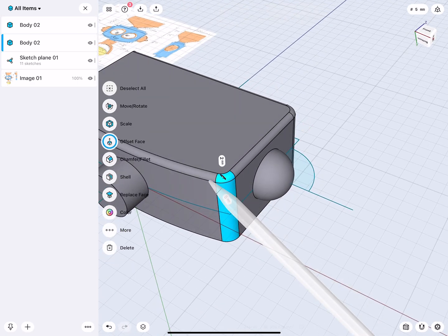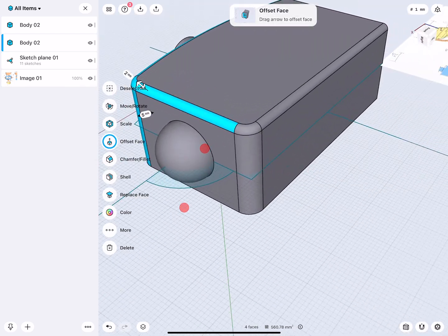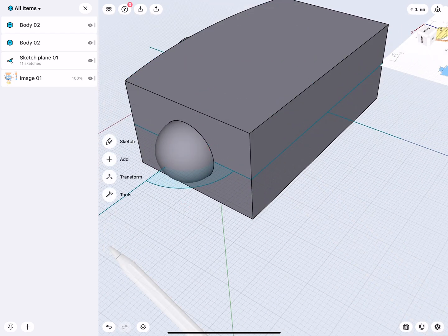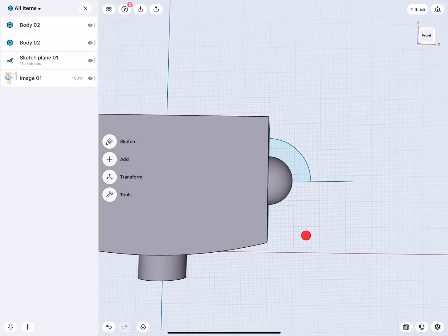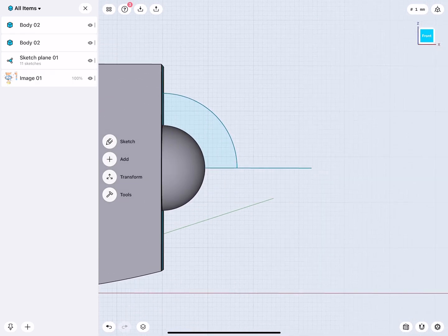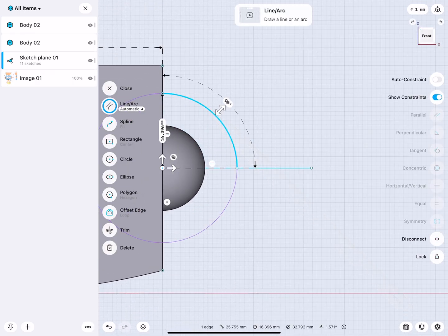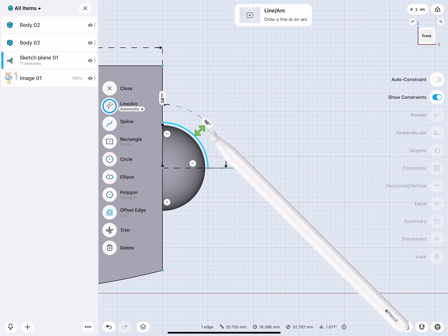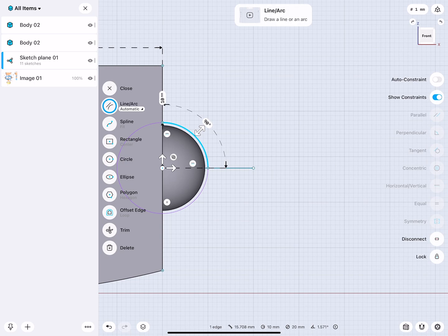Little tip for those who are not familiar with it, I filleted these corners here. I can select all these fillets and delete them. Then I have my original object back. And I hope you notice how I'm blocking out just only the basic elements and start playing and adjusting geometry and sketches. Now this comes back to when I said don't try to work too precise from the beginning, because things might change and evolve while we start modeling something.